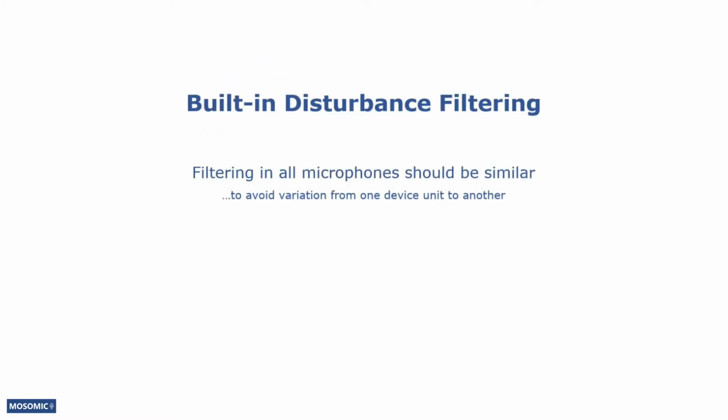If the device manufacturer uses microphones interchangeably from multiple microphone suppliers, the filtering in all the microphones should be similar to avoid variation from one device unit to another. This may be challenging to accomplish in practice.